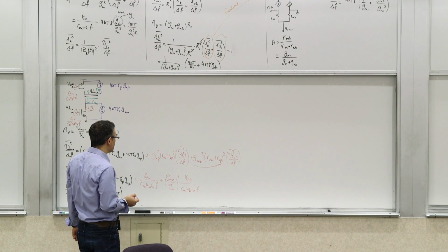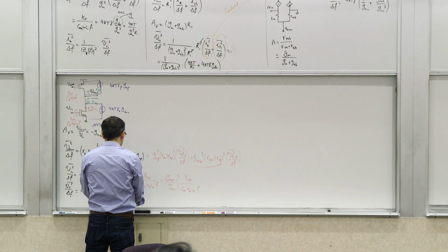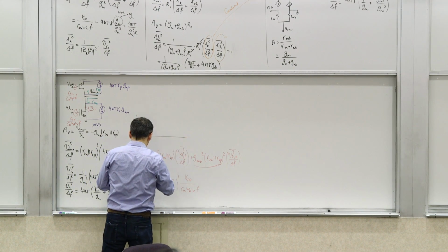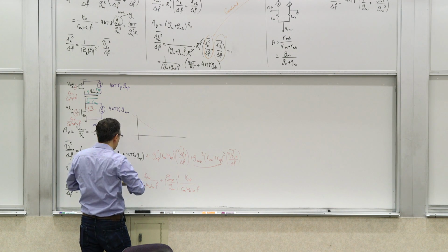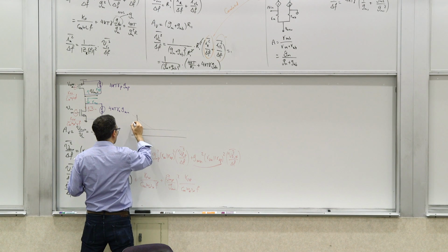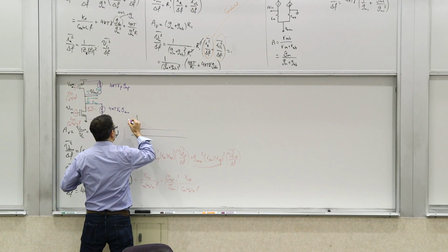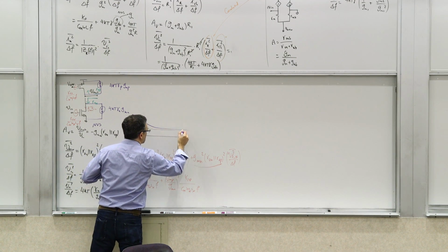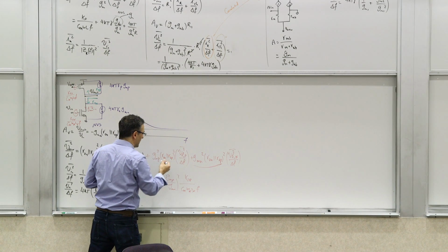So what you can see here is that, of course, these two terms are giving you 1 over F behavior. So if you look at the power spectral density of this noise, there are these guys that give you 1 over F noise behavior, and there are these black ones that give you flat noise behavior. So overall, you see a spectrum that looks like that versus frequency.